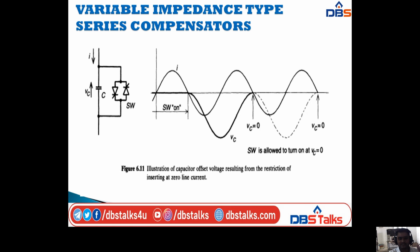So this circuit consists of one capacitor in parallel with the thyristor valve, also known as the switch. It shows the voltage across the capacitor and the line current. The first waveform, a pure sinusoidal waveform, gives the line current, and when the switch is on, the voltage waveform changes like this. Up to half a cycle it stays as a constant line.